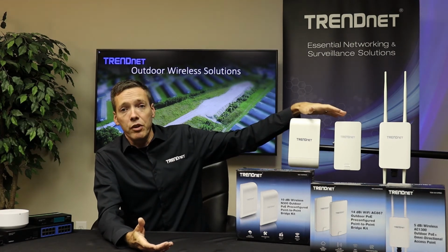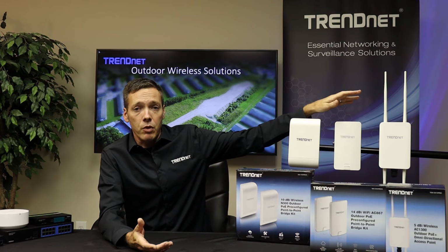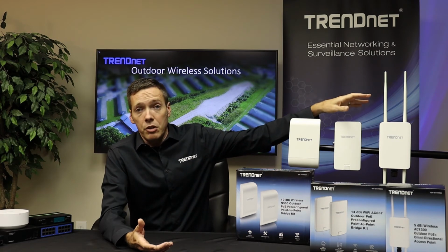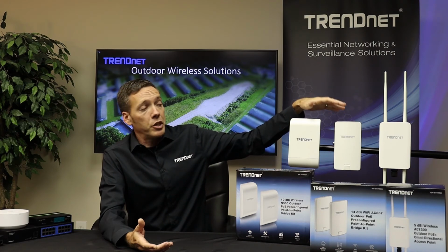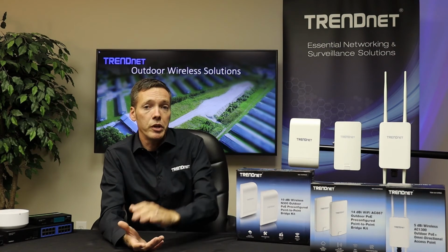That's the same with the 2.4 gig and the 5 gig directional. If you're talking about range on the omnidirectional, that is going to be a maximum of 1,800 feet. And that 1,800 feet is from an omnidirectional to another omnidirectional, or from an omnidirectional to one of the directional units, because of course you can do point-to-point and point-to-multipoint.